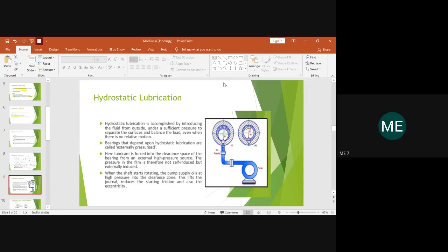After that, you should know that in hydrostatic lubrication you need an external pump, which helps in sending the required pressure for the fluid film. So we need an external media. How do you develop the required pressure? You have to use an external pump so that you apply pressure at the inlet of the oil, and hence the pressure of the oil at the inlet will be higher. If this is the inlet, P suffix naught will be the pressure of the oil within the inlet. You will have a pump which supplies the oil at a particular pressure so that the required film pressure is established.